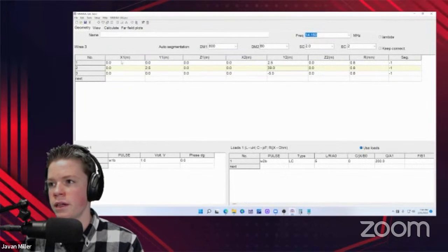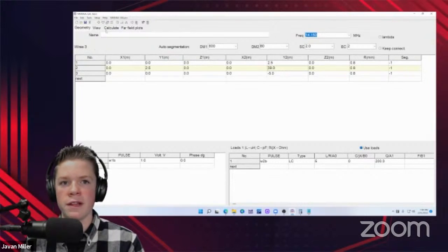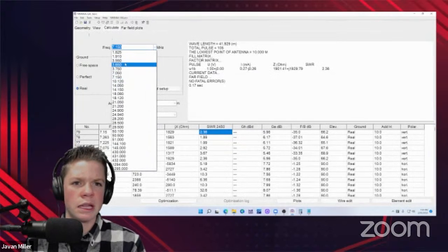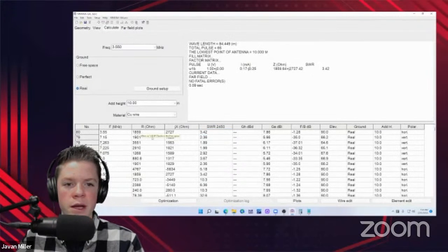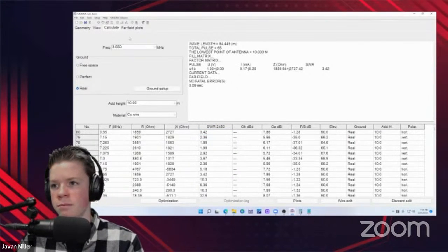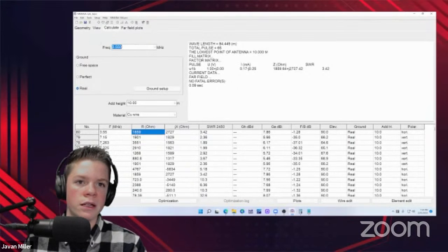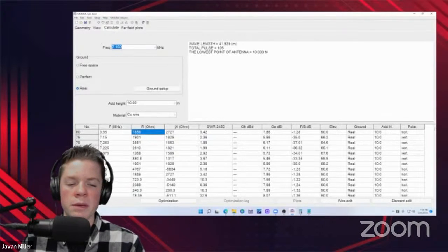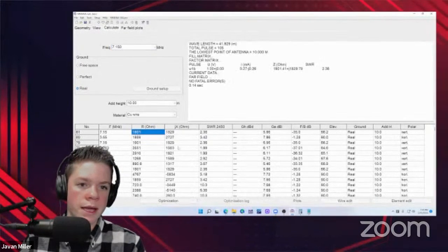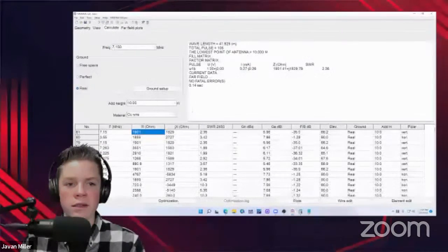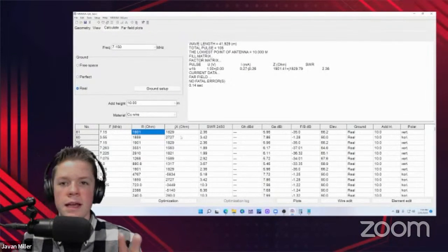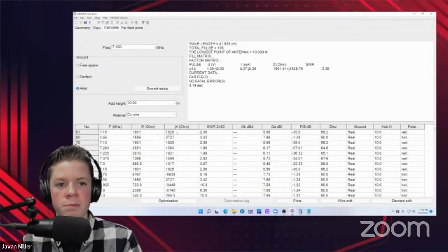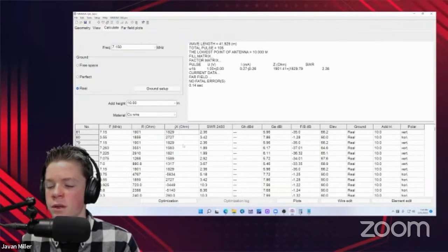So let's now look at the transformer, the 49 to 1 transformer, and see if that's really the best option. Let me do another test here. At 80 meters, we can see that it's around 2,000 ohms, so 49 to 1 is about perfect for that. Let's go over here to 40 meters, and we can see that this is about right. And you can see here that it's not exactly resonant. It's plus around 2000 j over here, so it's a little bit reactive.